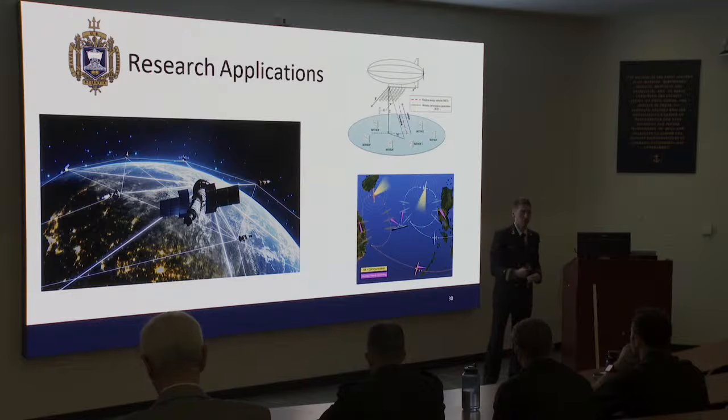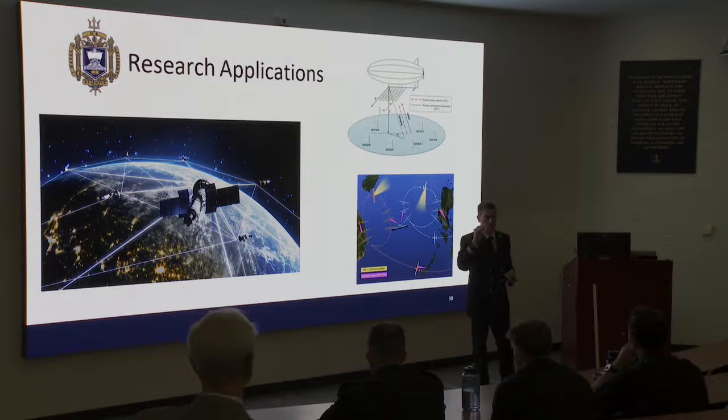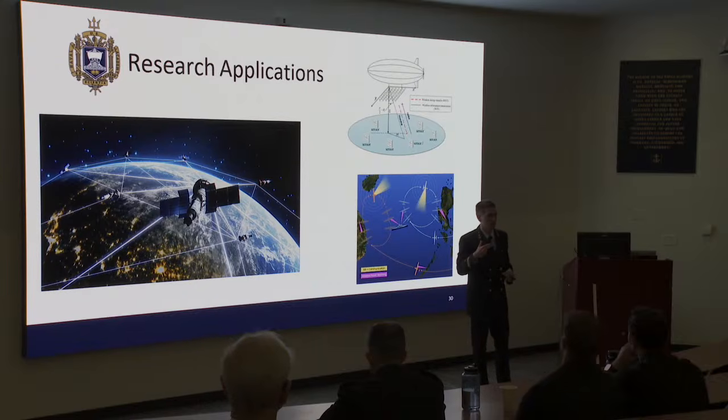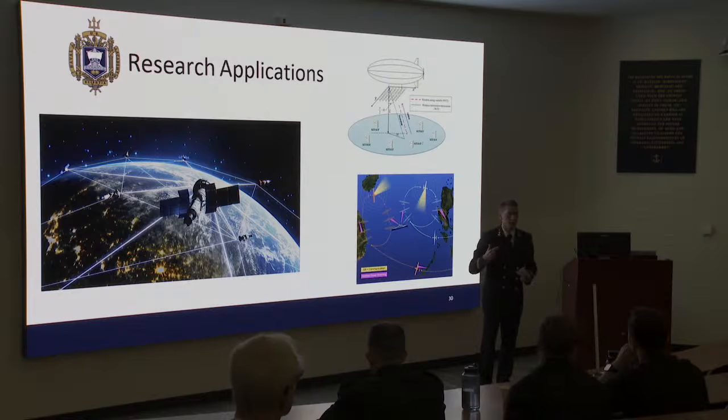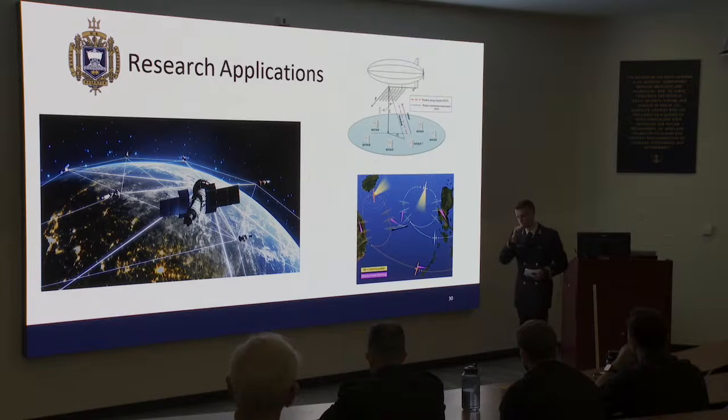Not only does this increase the communication speed, but it also increases the power efficiency because you're modulating the laser diode even less. Also, an advantage of a more refined DAC system is that we can also decrease the minimum step size of the system. A smaller minimum step size means that we can introduce even more distinguishable amplitudes and symbols into the system, meaning that we can transmit 5, 10, 15 bits per signal being transmitted, dramatically increasing the speed of communication.